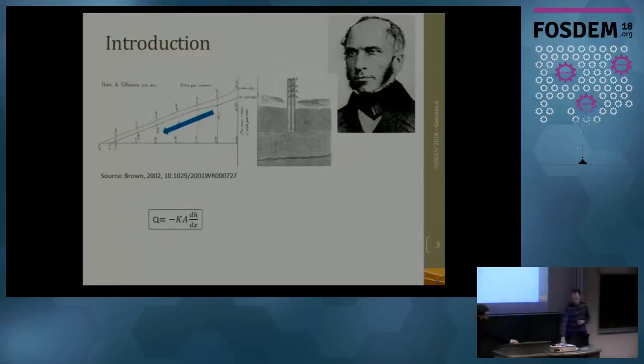As we know it today, it started about 200 years ago, a bit less, with an engineer called Darcy, who came up with the idea that groundwater flows from high to low pressure following a certain constant, this K in his equation, which is called hydraulic conductivity. It's a value related to properties of the soil, like porosity and grain size, etc.